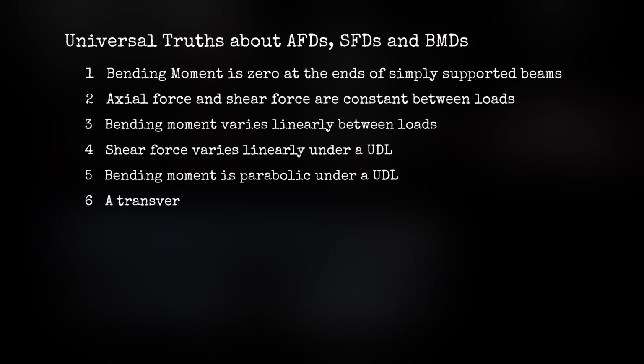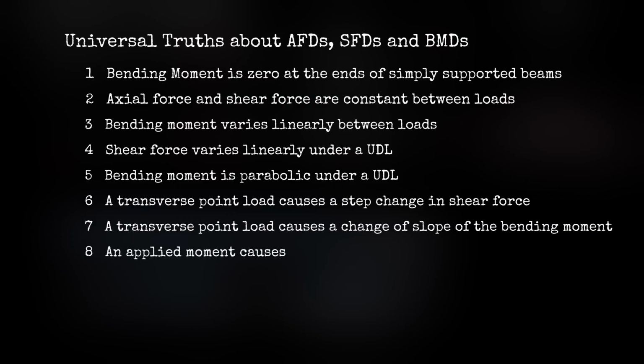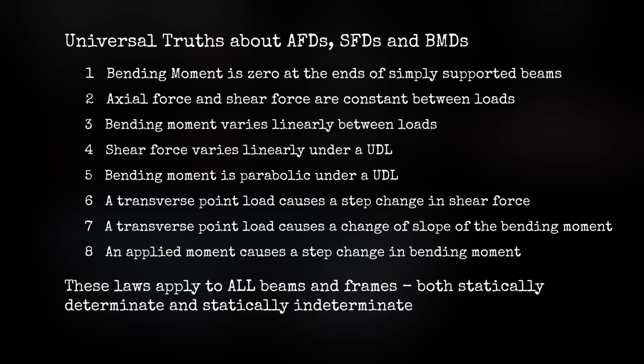6. A transverse point load causes a step change in shear force. 7. A transverse point load causes a change of the slope of the bending moment. 8. An applied moment causes a step change in bending moment. These laws apply to all beams and frames, both statically determinate and statically indeterminate.